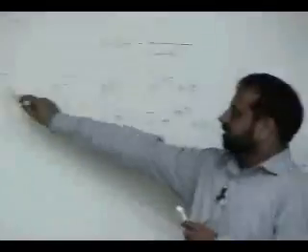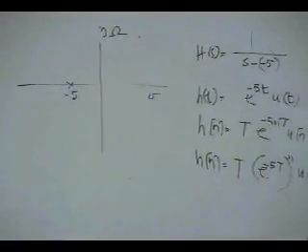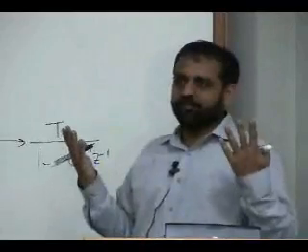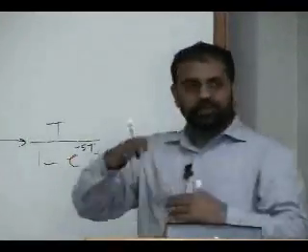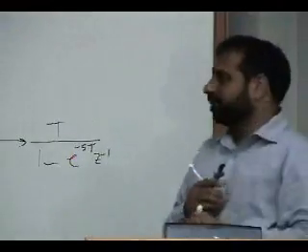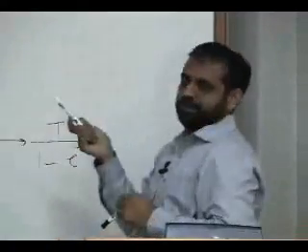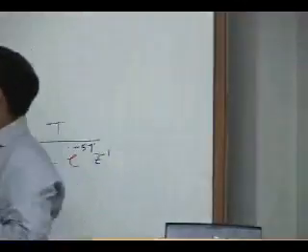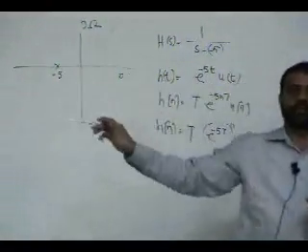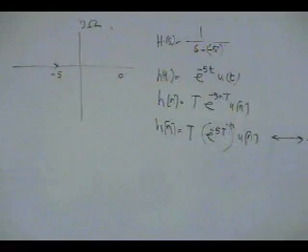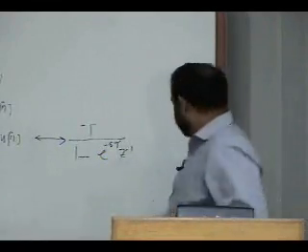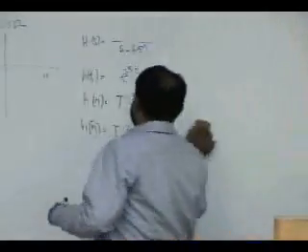A pole here will be an exponential of minus 5 times T. You can keep T equal to 1 because T, remember, does not really matter. So a pole there is an exponential of the pole in the Z domain. Once you convert from here to here, you can directly convert instead of going through all this. Looking at this, you know it is 1 over 1 minus exponential minus 5 z inverse. So this is the answer from Hc(s) to H(z). And then you can plot the pole location.